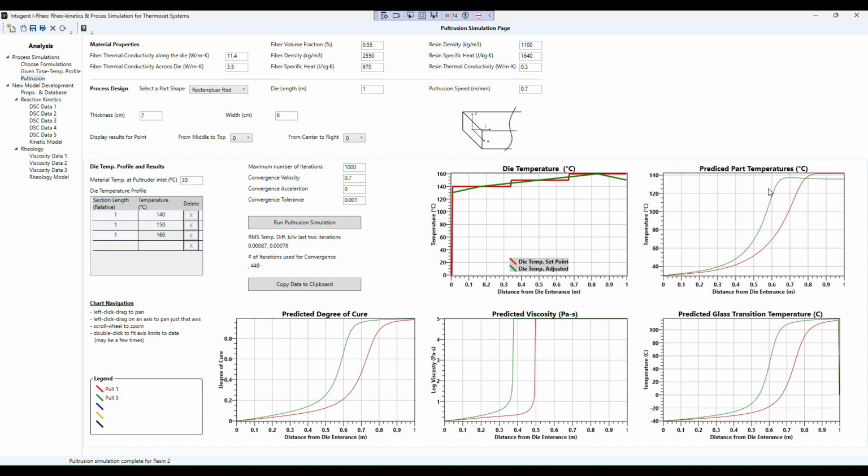The max in the temperature profile at the middle of the part must be within the die to avoid cracking issues due to thermal stresses. Resin Pull 3 is more reactive than Pull 1. It can be run at higher pultrusion rates. With everything else equal, we'll prefer Pull 3 over Pull 1.